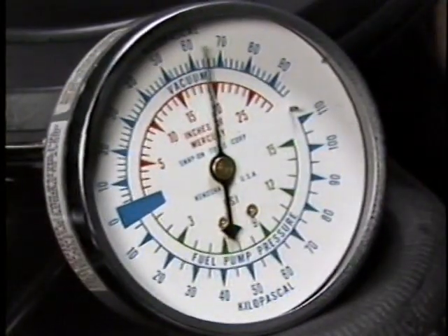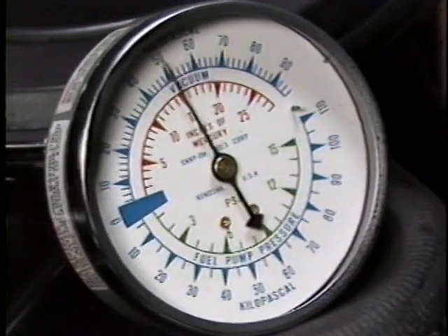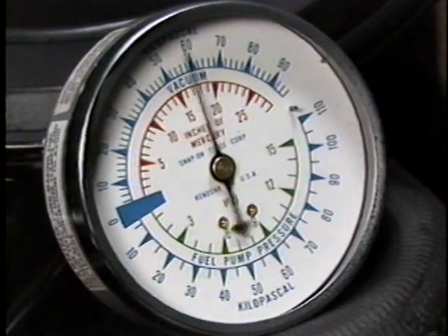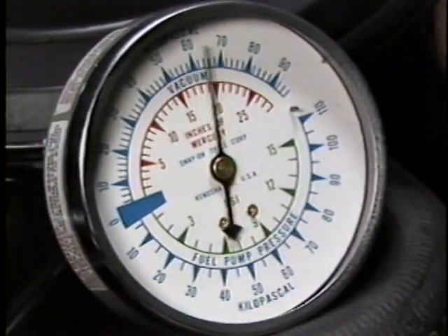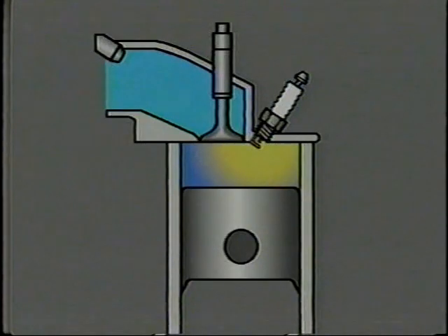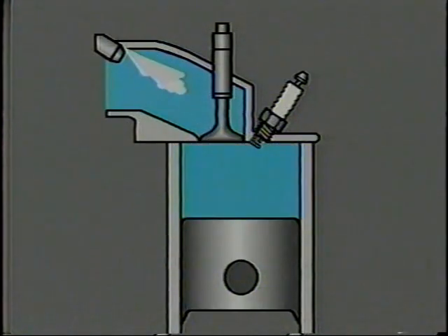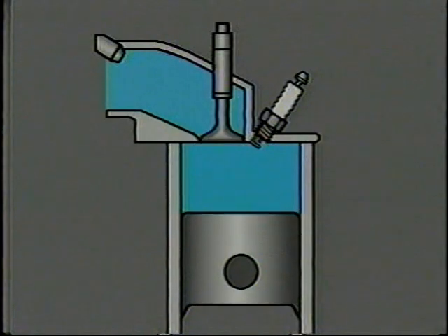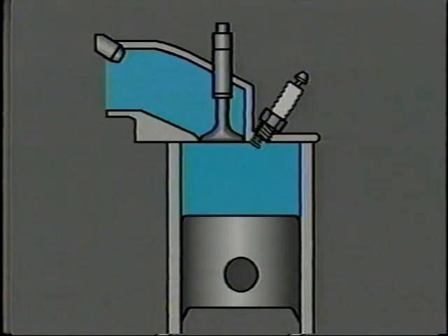If the needle on your vacuum gauge fluctuates or drops back, it suggests that for some reason the individual cylinders are not drawing in the same amount of airflow. A fluctuating vacuum signal may be caused by leaky or sticking valves, a leaky head gasket, certain types of intake manifold gasket leaks, or an ignition system fault or fuel system fault. Each of these results in one or more cylinders not firing properly or producing its share of power.